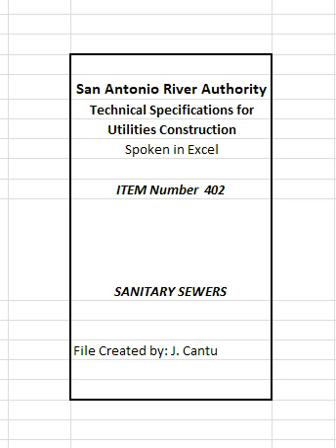Should coupled joints of pipe be out of line or off grade, they shall be removed one joint at a time and brought to the proper line and grade. The lifting or moving of several joints of coupled pipe at one time to close a partially open joint or to fine grade underlaid joints of pipe will not be permitted. Pulling or pushing a joint of pipe in place by using a crane, bulldozer, or backhoe will not be permitted.